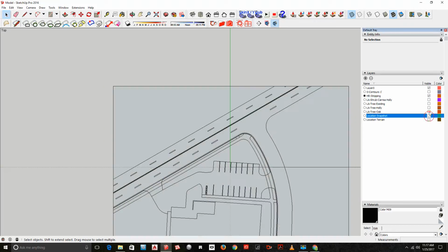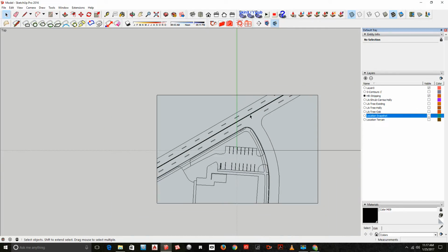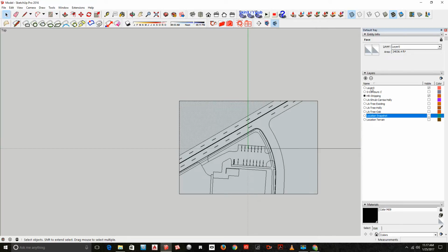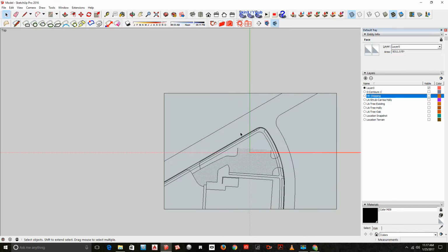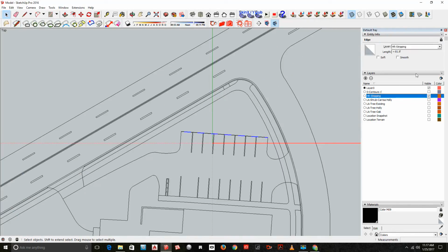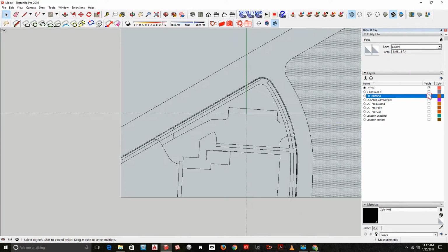Now I do like to put, let me turn everything else off. And all this is kind of layers. Let me put myself on layer 0 and turn my striping off. That way too, it's important. That line is on striping, I don't want it to be there, so that should be on layer 0. So you can see these things. Layer control again is super important.